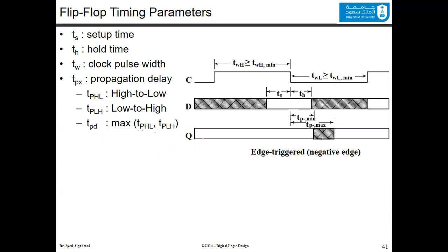So you will have a minimum time of the circuit, and you will have a maximum time. You will get the maximum from those two times, and you will consider that to be the propagation delay. To explain this also in a circuit, let's say we have this circuit where you have an OR, with one input inverted and the other inputs going through an XOR, and after the XOR, going through an AND circuit this way.